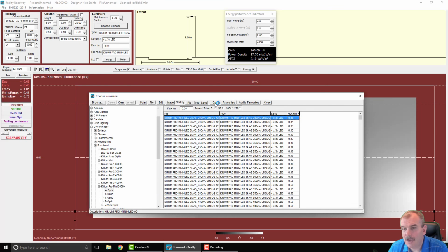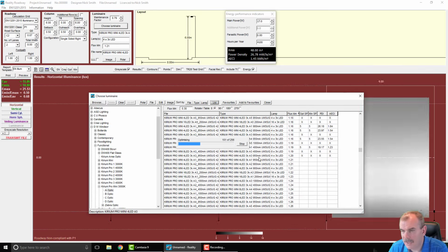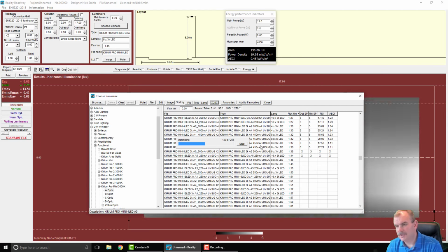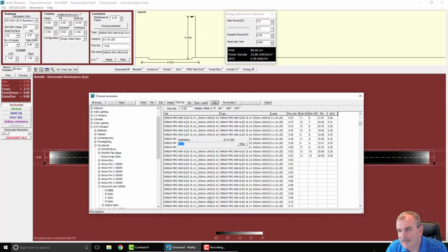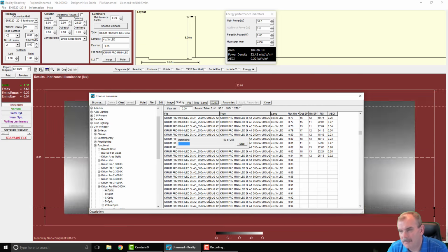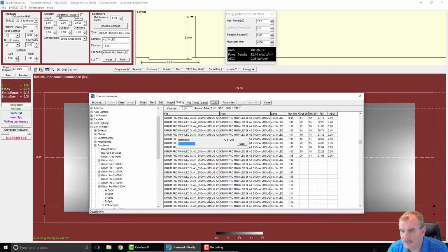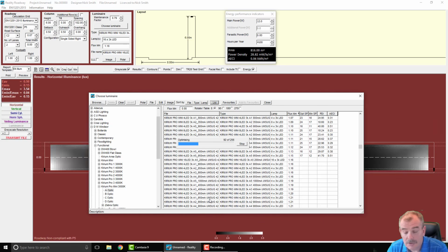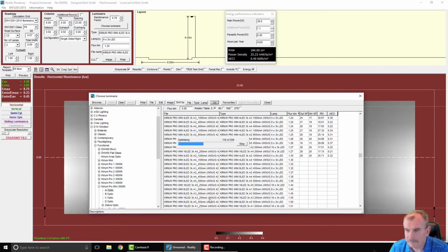So when we go into the optimization box here, you can see initially it was producing no results. Actually, let's not do a P1. Let's try and do something a bit more realistic. Let's go with a P5. So we're looking for an average of 3 and a minimum of 0.6, and as it's going through that, it's calculating an optimum and a minimum spacing, and it's also calculating the power density and the annual energy consumption indicator. 256 options, so a little bit of time for it to calculate that.